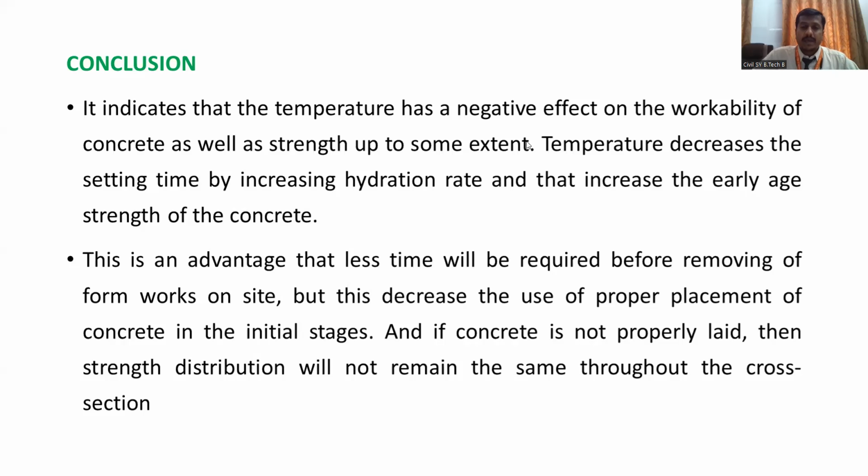Otherwise, in daytime, what will happen? One part of concrete is hardened and one part of concrete is in fresh condition. So it is difficult for us to bond it together. Okay. So there are several factors like this. That is why we'll always prefer concreting at night time. And regarding heat of hydration, whether it is good or bad, I think I have given you a satisfactory answer. We need to consider the suitability, what type of construction we are interested to construct. Depending upon that, the heat of hydration process will be there. Clear? Yes, sir. Clear. Okay, good.